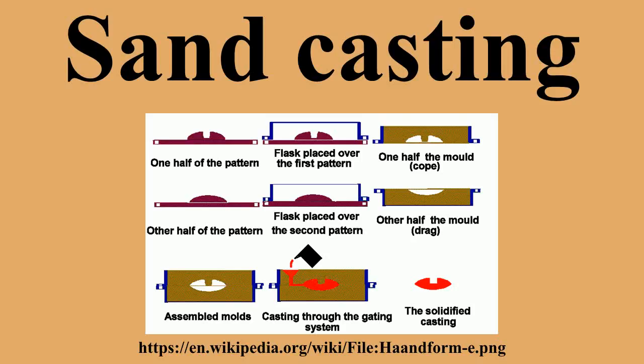Although very fast, vertically parted molds are not typically used by jobbing foundries due to the specialized tooling needed to run on these machines. Cores need to be set with a core mask as opposed to by hand, and must hang in the mold as opposed to being set on the parting surface.